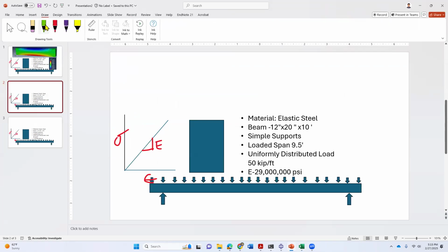So I want to draw here that if we model the material as elastic plastic, the steel stress strain response goes linearly up like this, and then at yield point it goes like this, and then it continues like this. So we see some hardening too. As I said, as long as we don't have the test results from a tensile test, we can model this behavior using linear elastic and linear plastic, perfectly plastic, or sometimes we use